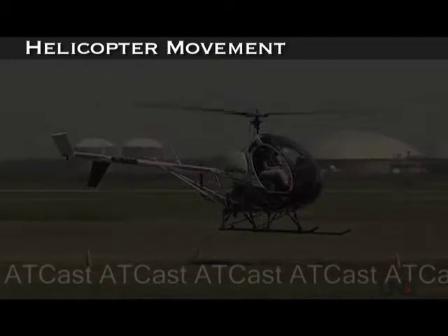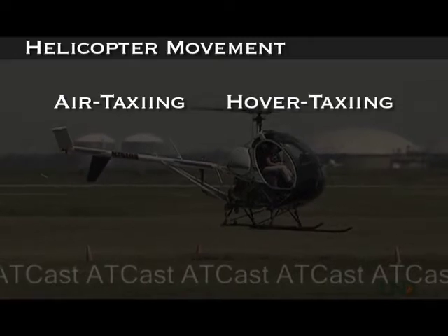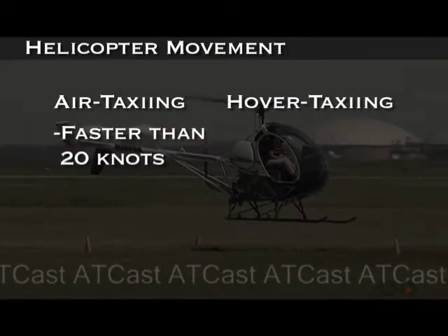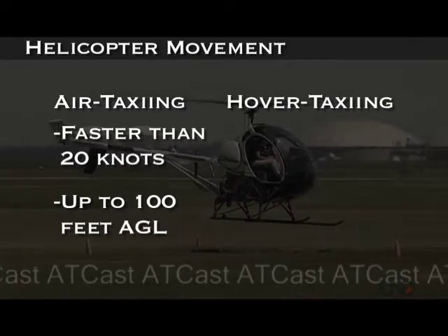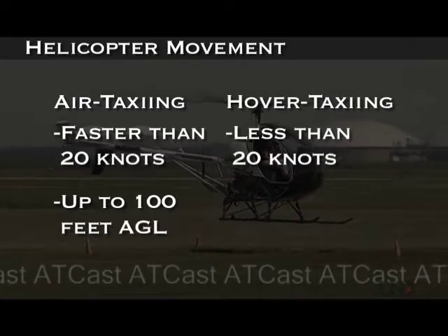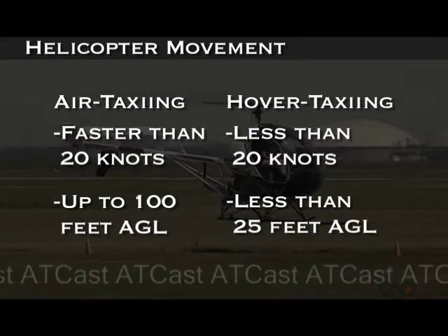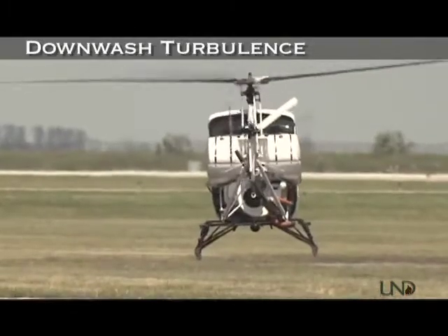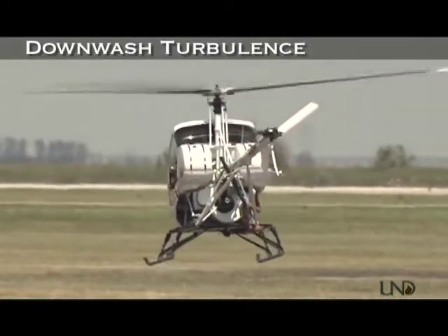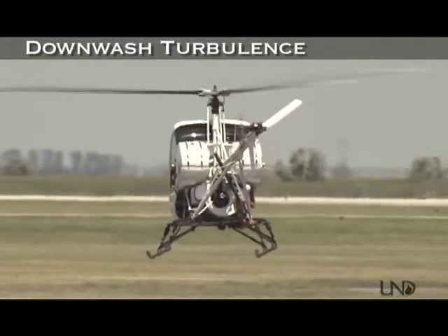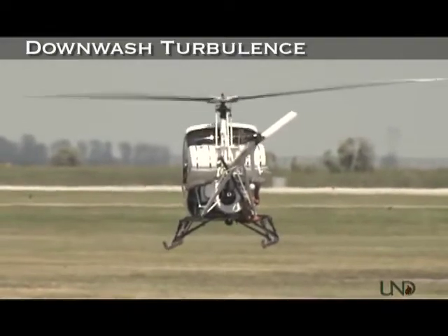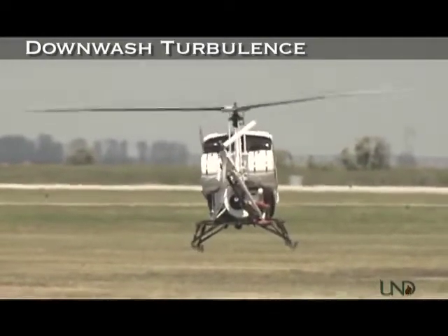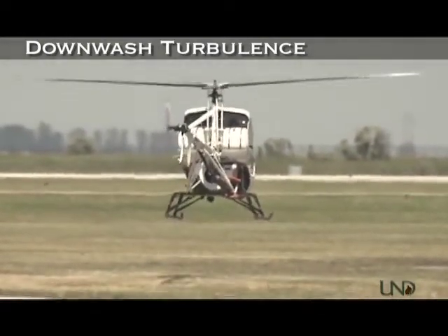The main difference between the two is the speed and altitude. Air taxiing can be faster than 20 knots and higher off the ground, up to 100 feet AGL. Hover taxiing is normally at speeds less than 20 knots and around 25 feet AGL. These operations can produce lots of downwash turbulence from the helicopter's rotors, which can stir up dust, snow, or debris. Be mindful of other aircraft, personnel, or vehicles operating near the helicopter, and provide cautionary advisories as necessary.